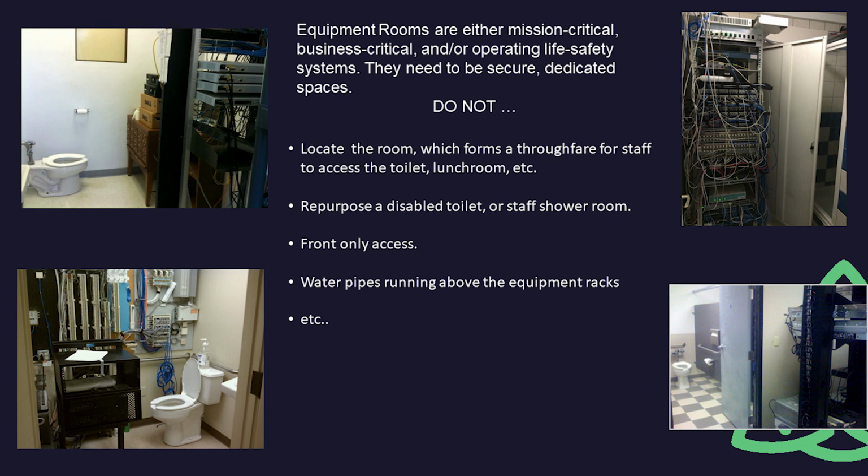All fire barrier penetrations should be mechanical and reopenable to support cable changes. Fire barrier penetrations must not be sealed by means of pillows or solid-setting caulking compounds. Fire retardant caulking may be used to seal electrical switchboard glands. A powder-type fire extinguisher suitable for electrical fires must be located inside the room, next to the door.